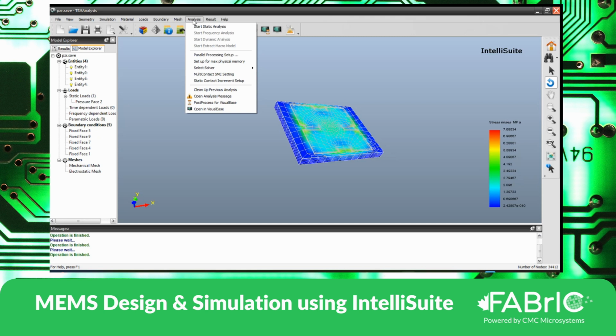Yes. For piezo-resistive type, yes, because based on the pressure that gets applied, the deformation will change. Deformation changes because the stress is different or it is more. So due to the deformation, the piezo resistors will expand. If the deformation is more, then the piezoresistive expansion is much more. That will change the resistivity, due to which the change in resistance causes the change in voltage drop.